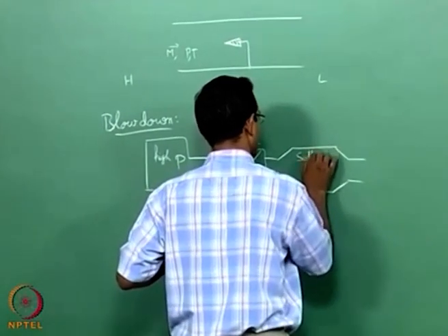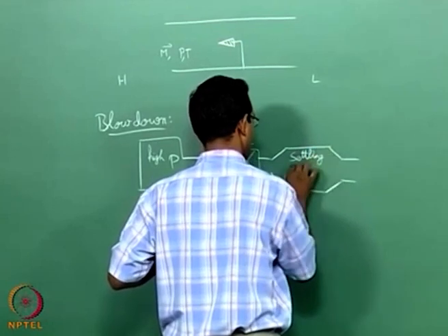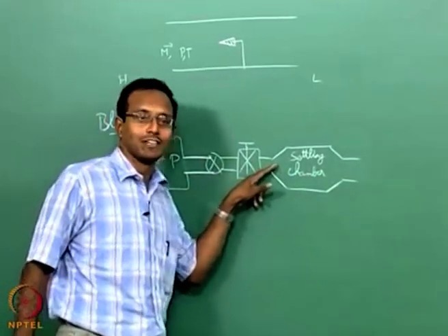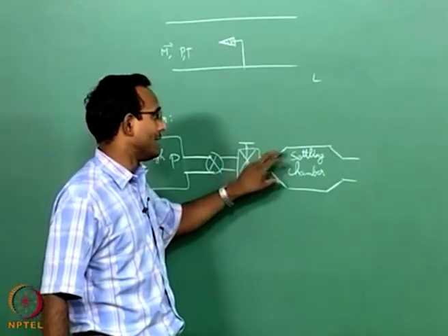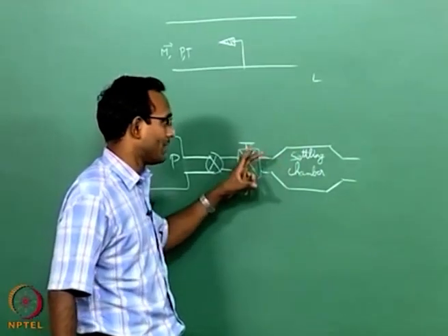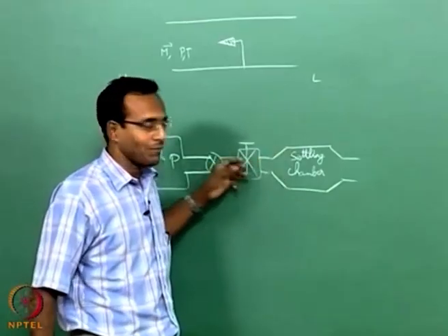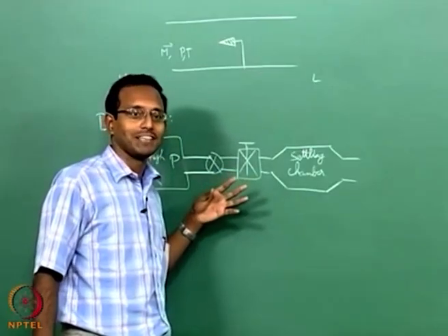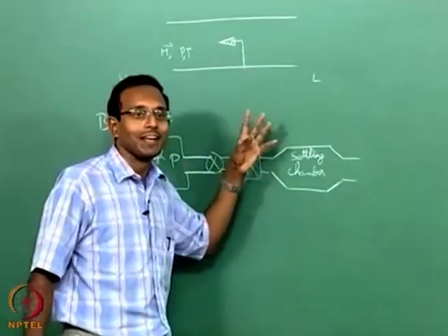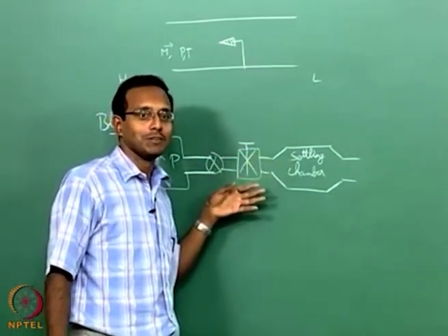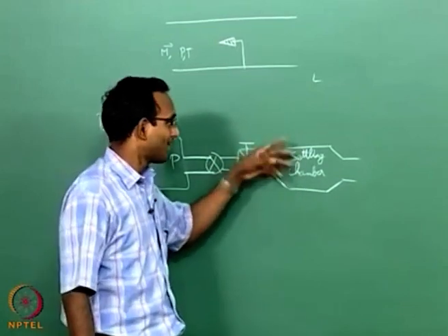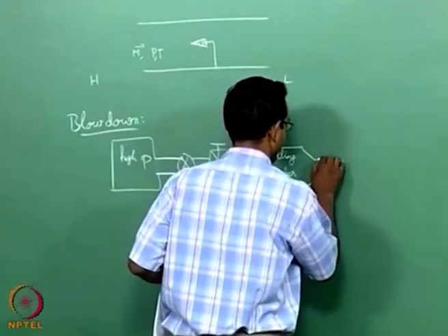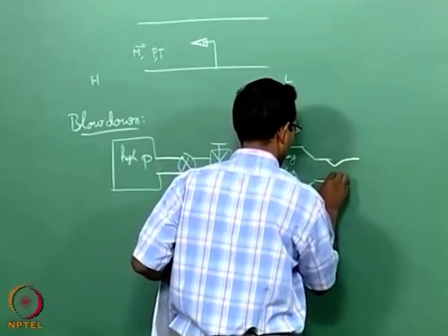Settling chamber. If there are any fluctuations in pressure or velocity, all those will be lessened if it is going through this one. Why? The area change is so high that for this mass flow rate the velocity inside here will be very, very low, and for very low velocities turbulence does not exist. So, it is almost laminarized and the velocities are so low, disturbances will die down very fast. Okay. And after that I am going to accelerate it and take it through to my test section with an appropriate nozzle in here to get appropriate Mach numbers.